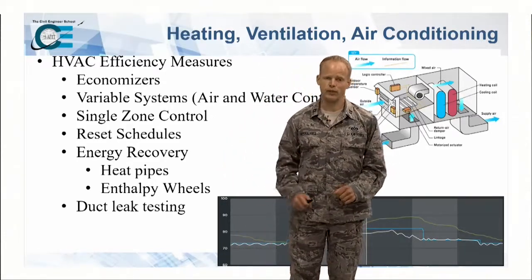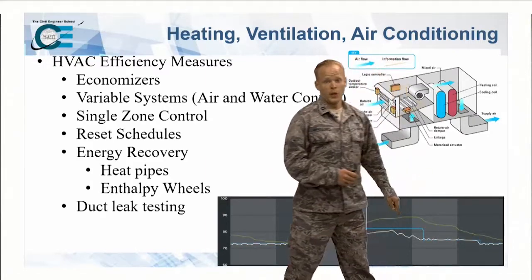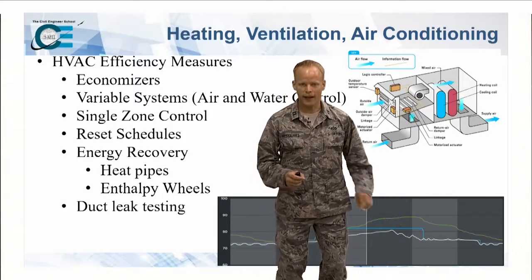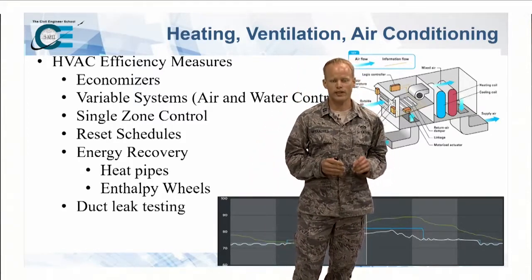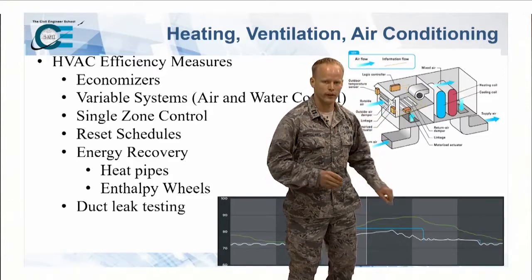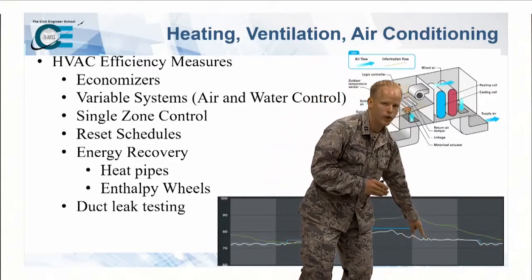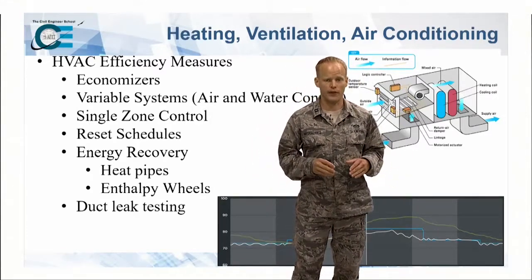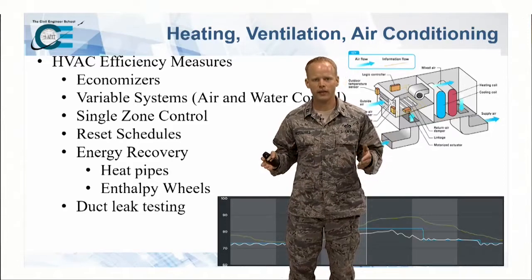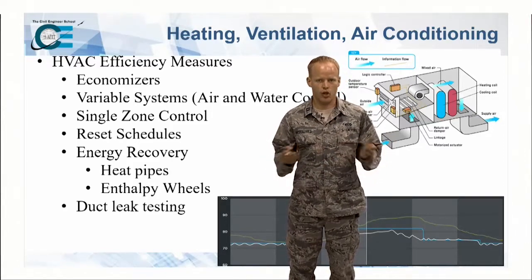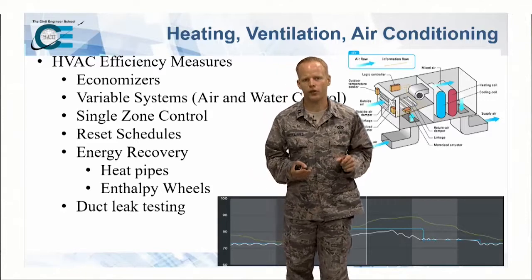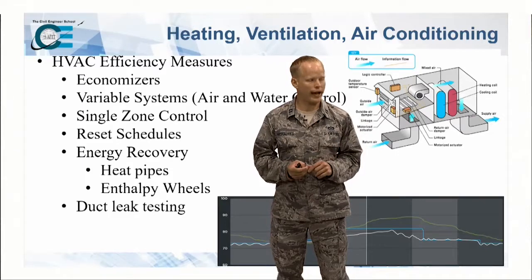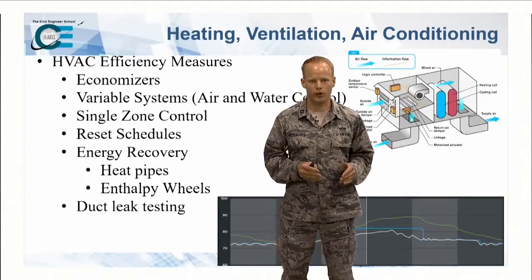Then, over here, let's go over here. Trying to figure out where to stand on here. Right about here, the Ecobee kicks on. I think it's using some kind of predictive control, so it's nice and cool and meets my set point when I arrive back at home at night. So opposite reset schedule. If you were to do this for your office building, it would be opposite. At night, you'll decrease it to say 80 degrees because nobody is in here. But you will still have to use temperature control, mainly for humidity. You can't get it too hot, and then you have to ramp up early in the morning.